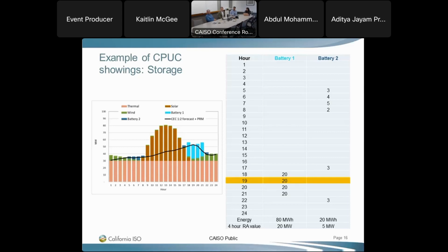And then my other question is, let's say you have a 2-hour battery, would you be able to show that at the CAISO for any QC? Or does it have to be at least 4? The 1-hour battery can be shown too. It's an equivalent: the megawatt hours of the resource divided by 4, limited by the PMAX. That's a PUC ruling. That's what gets transmitted to the ISO.